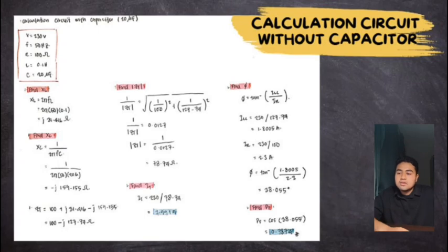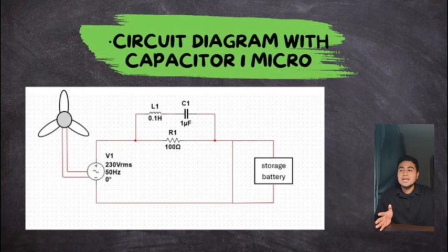If we look at the total current from the simulation, it is 3.191, while the calculation is 2.991. So actually it's close. Maybe in the calculation we skipped the decimal numbers and took shortcuts here and there, so the result is slightly different, but I can say that our simulation was on the right track.